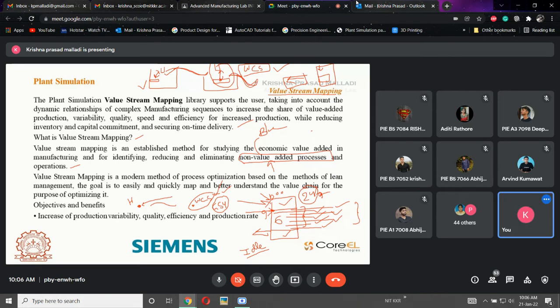That is why the majority of machines won't switch off after a particular time. They will be in a running state, but kept in an idle state. Which means the spindle is going to stop and everything will be in a stopped condition, but the machine has a power supply and everything is there. The machine is at the G54 location. So if I stop it, then there will be a lot of issues. That is why it is kept on.